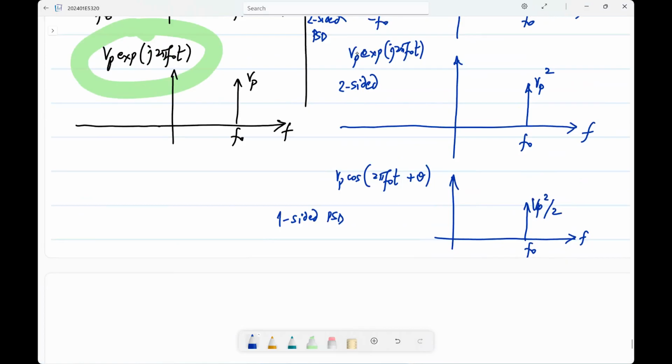So whether you integrate one-sided spectral density or two-sided spectral density, you should get the same answer. So that's why you show only one side of it, but double all the components. That's all there is to it, because it's symmetric after all. So you can think of it as folding and adding. Is this fine? This one-sided PSD is what we will use for describing our noise sources also. So eventually you will have to do calculations with this one-sided PSD. But of course, if you had occasion to use two-sided PSD, that's also easy.